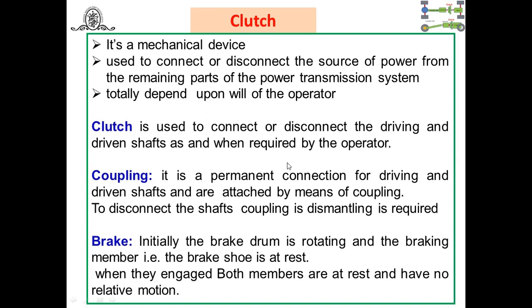But there are other mechanical elements, such as couplings and brakes, which are also used to connect driving and driven shafts. But there is some difference. Let us see. The coupling is a permanent connection. On the driving shaft and the driven plate, they are coupled by using nuts and bolts. That means it is a permanent connection, and to disconnect the shafts, coupling dismantling is required.